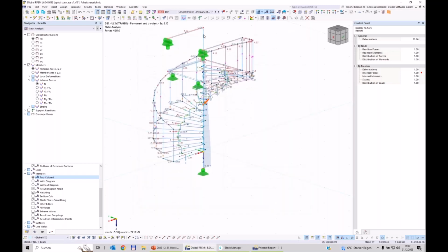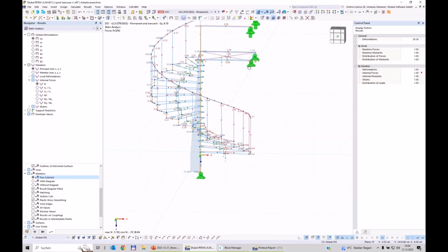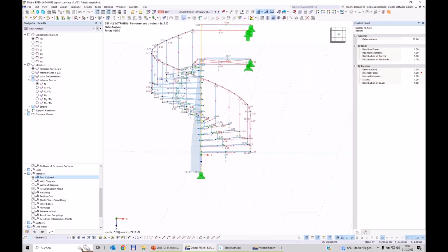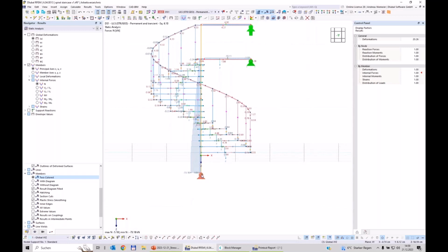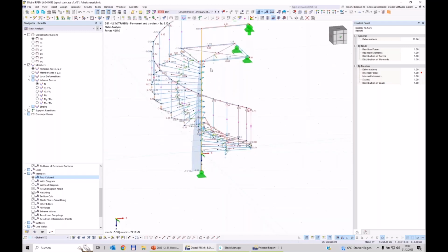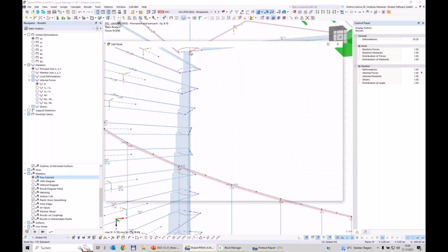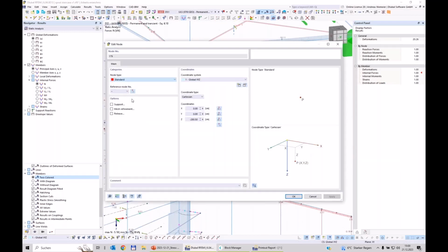And we say, okay, for this vertical column, when we watch it from the lateral side, so maybe in this direction, you see it's maybe hinged here, and this is let's say fixed here on this place, more or less horizontal. So I use maybe a pendulum column idea between these two situations. I place a node on this member. So I say this is a node on member.